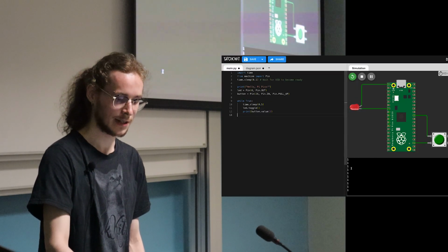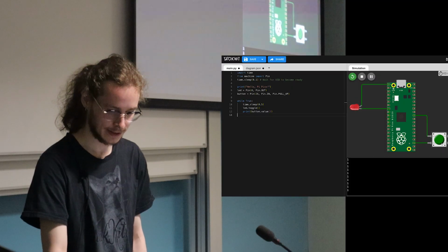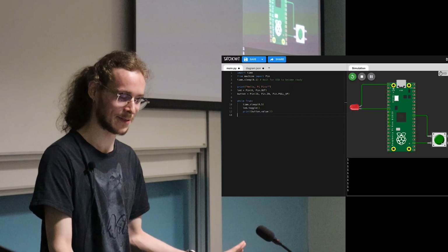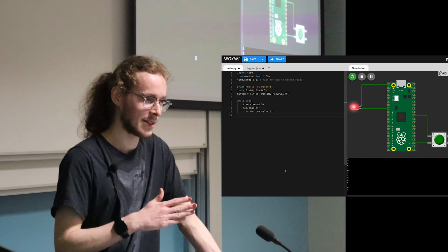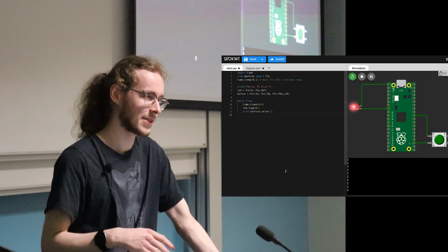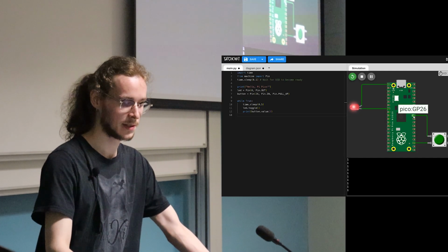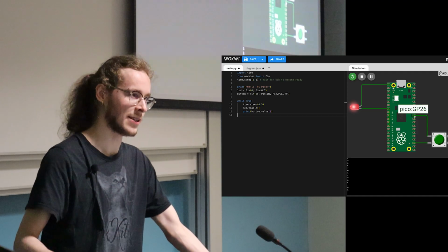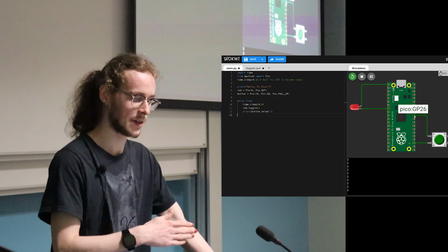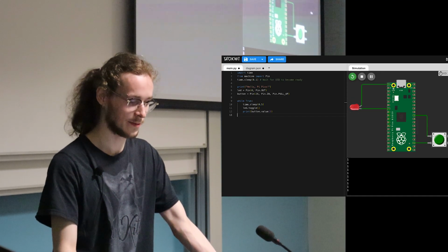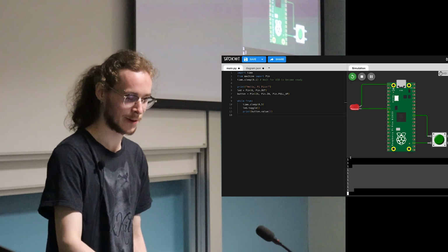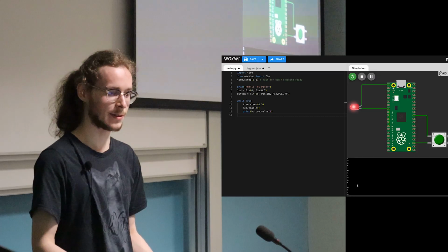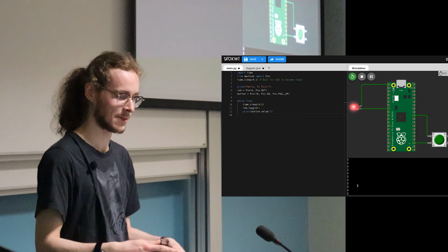And if I press the button, that I don't think, actually no, okay, ignore that. But for now, it's going to show us ones because we've connected this loose pin, not connected to anything, to 3.3 volts. So a high voltage. So it's showing ones now, whereas it would be showing zeros sometimes, ones sometimes.